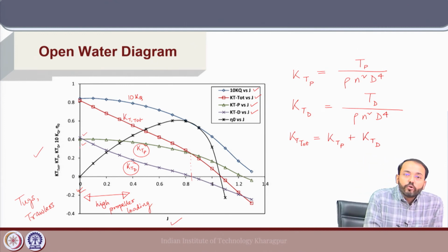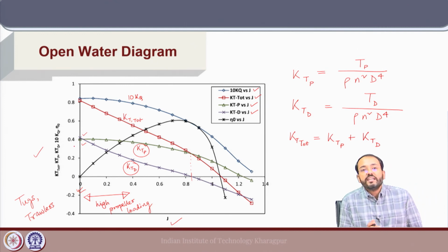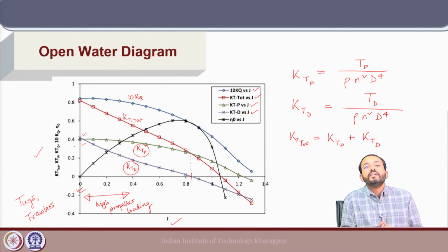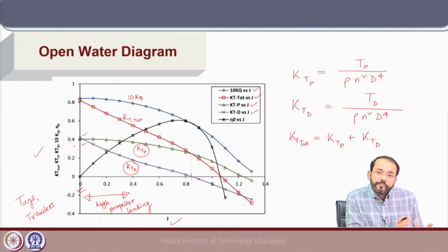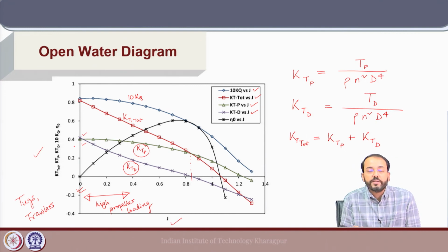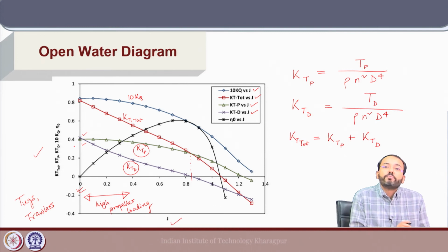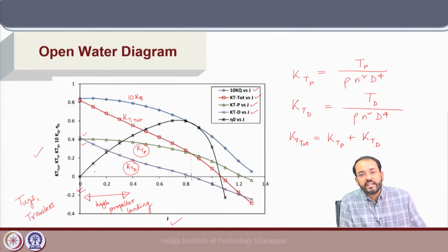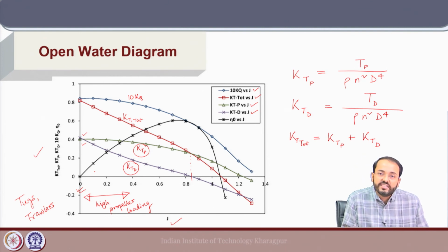And close to the Bollard condition, we see that the thrust ratio tau is almost equal to 0.5. That means the portion of thrust produced by the propeller is almost half that of the total thrust, because the thrust coefficient of the propeller as well as the duct are very similar. It will depend on the propeller and duct designs for specific applications.